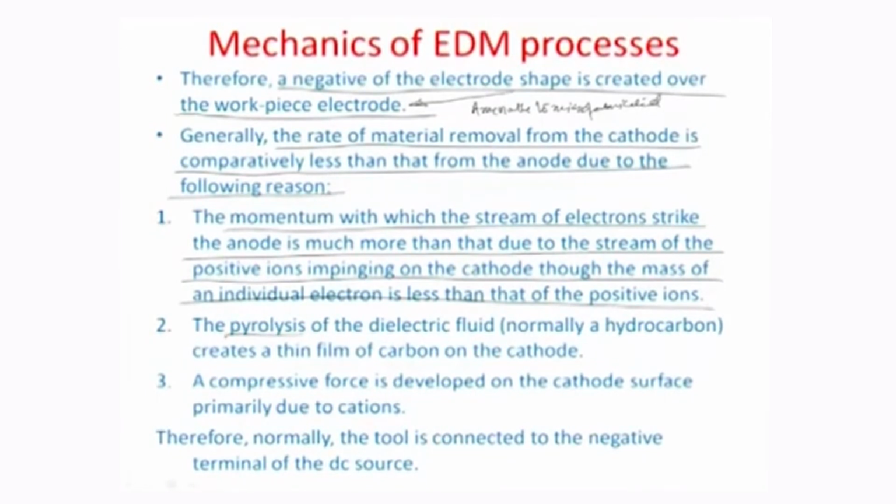the pyrolysis, and particularly the pyrolysis of the dielectric fluid, which is normally a hydrocarbon. As I have already illustrated many times before, in the EDM process there is always a medium in between the cathode and the anode, and that is typically one with a high dielectric constant and is an insulating medium. So the question of breakdown only arises when such high dielectric fluids are circulated, and hydrocarbons are the most prominent ones because they themselves do not participate in forming oxides or nitrides and so on of the material on the surface. It is a high temperature melting process of machining that we are talking about.